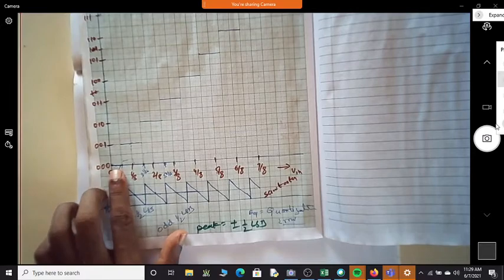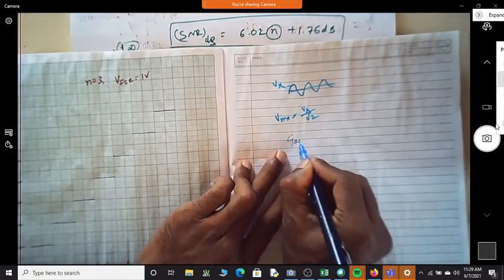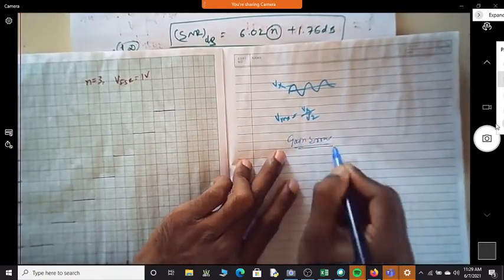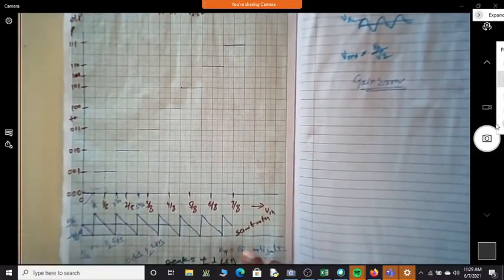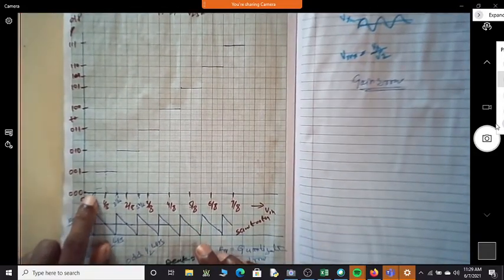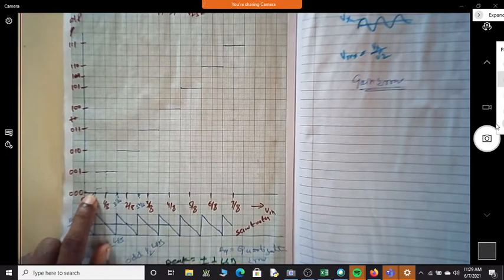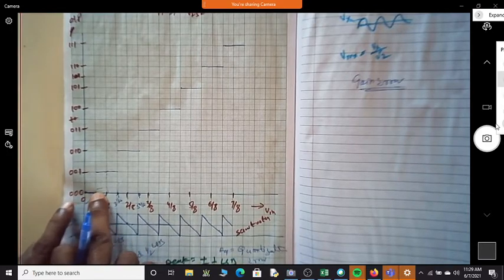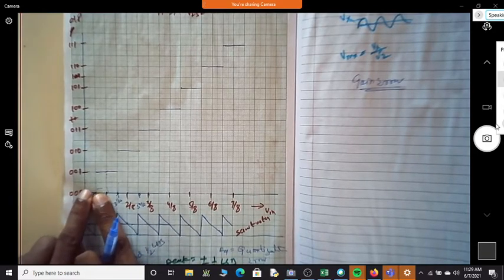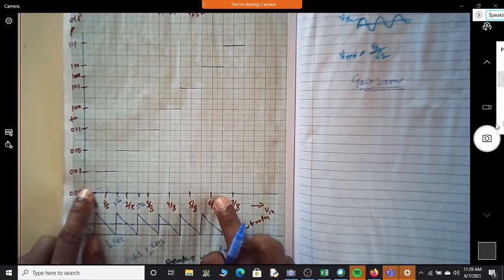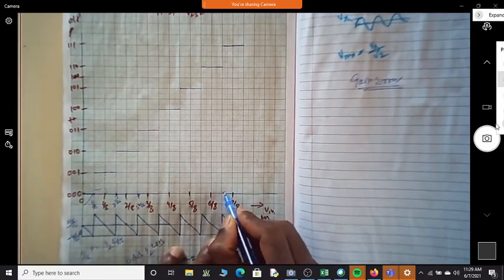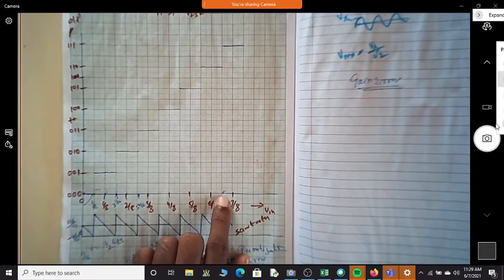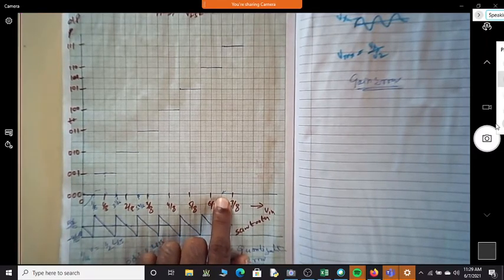Okay, that's what you mean by offset error. Then I'll have gain error. This is gain error. Where is your first transition happening ideally? First transition happening ideally at the half LSB. Where is the last transition happening? Is it happening here? Is it happening here?